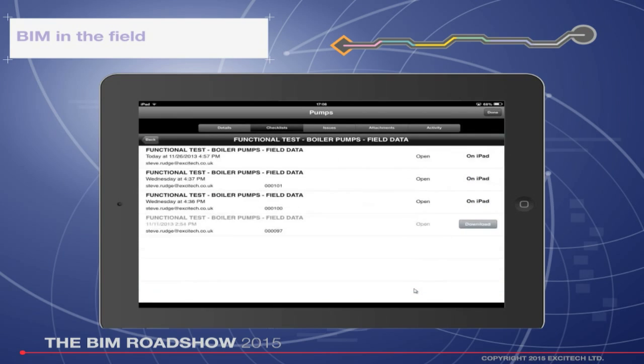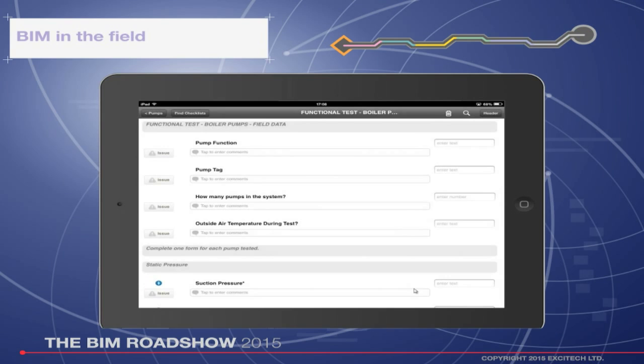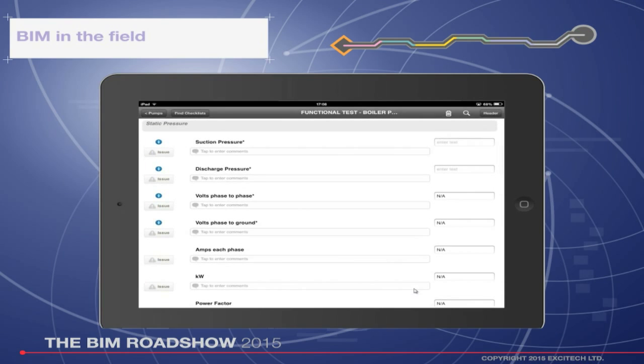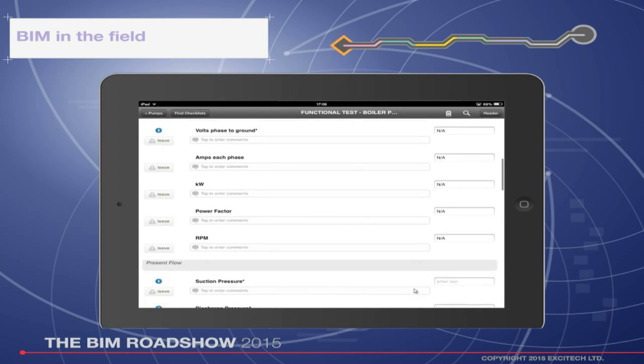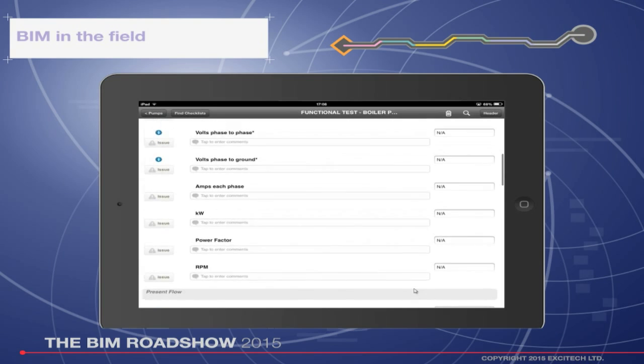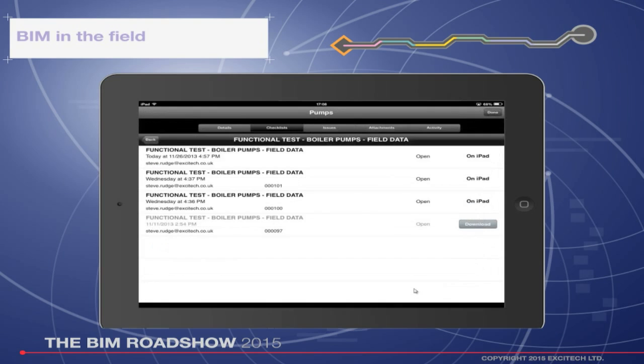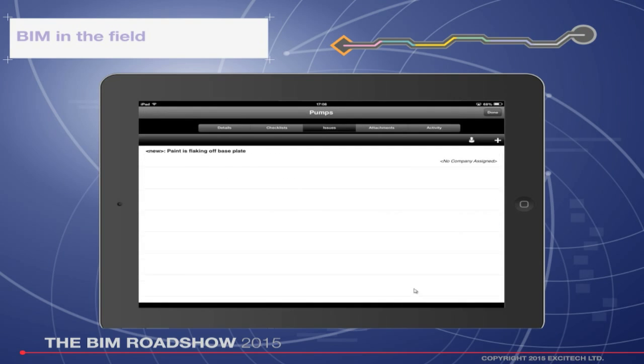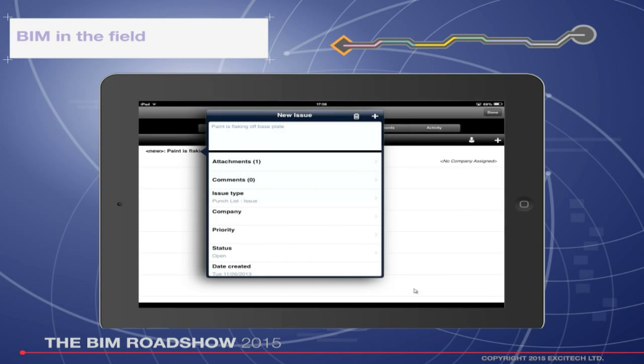And I mentioned earlier in the bid stage that we've actually got things linked to it for testing, for functional testing and things like that. Sort of things that we need to fulfill. So before I do any work on that pump, I need to go through this and sign off that I've actually isolated the power, I've isolated the feed, etc., to the pump, and it's against me.